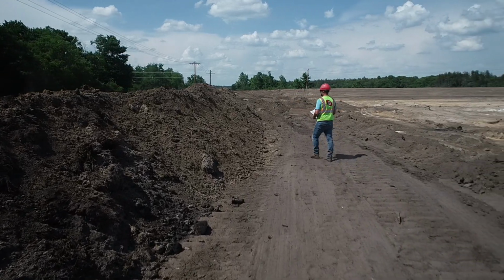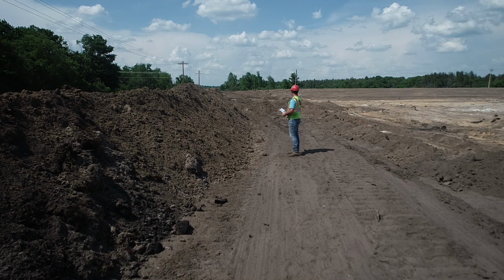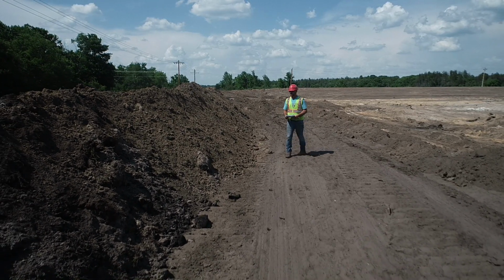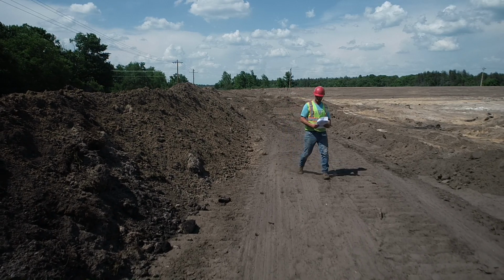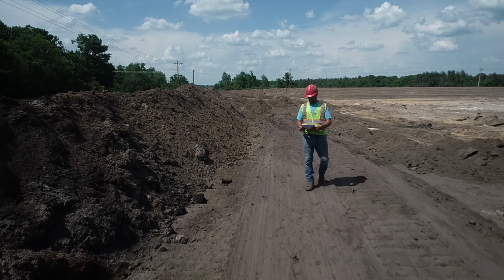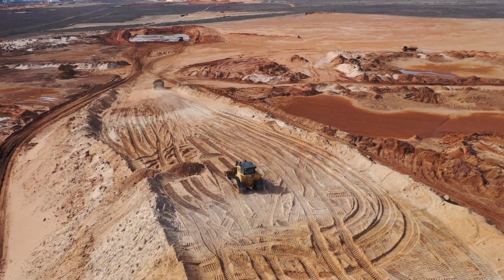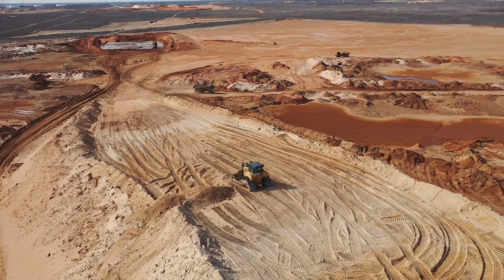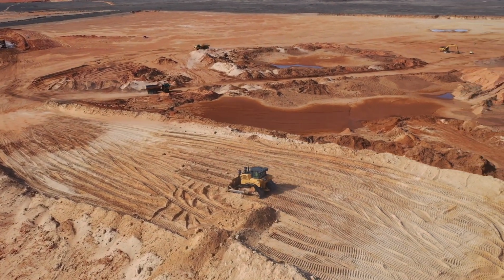Stop, observe, and assess the slope before working on it. Perform additional checks during the work shift to ensure ground conditions have not changed when the edge of a slope cannot be seen from the operator's position. Grade positioning. Proper gear selection must be used to maintain control. Drive according to terrain conditions.